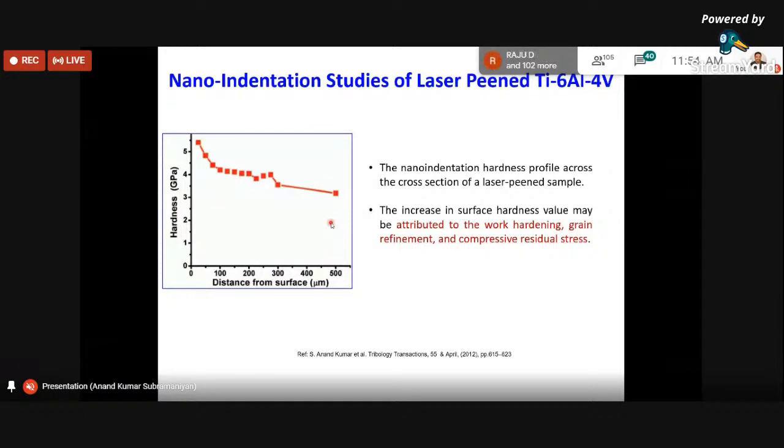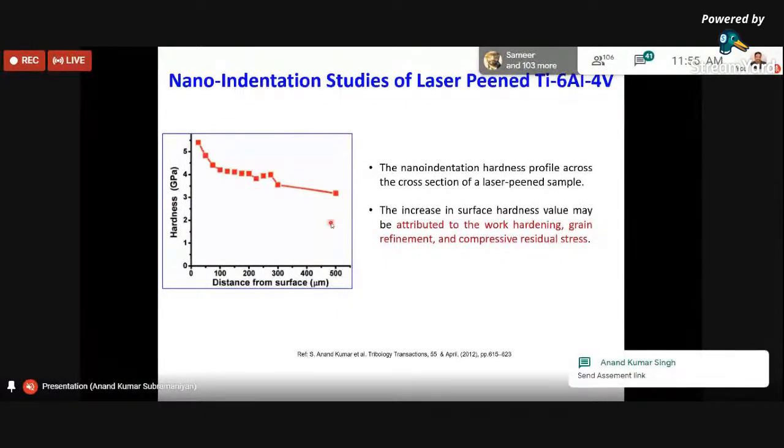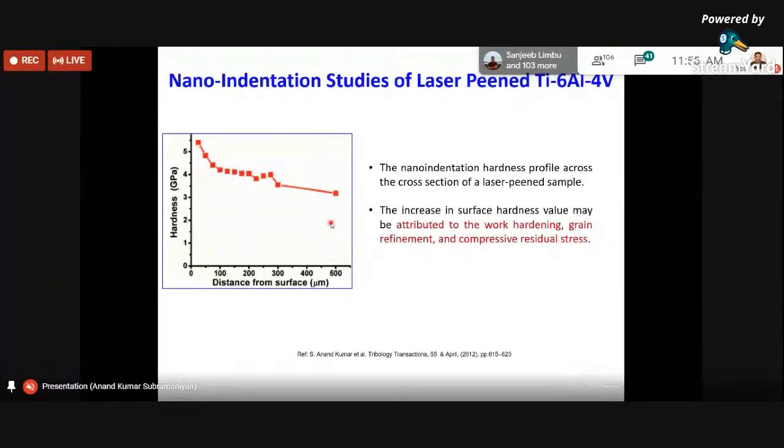Oh, well, this is a very open-ended question. It actually depends on what material we want to process, right? The key characteristic of the ball is that it has to be harder than your substrate material. That is one of the key properties to focus on while selecting the ball, and that also is correlated with the sample that we are going to process.